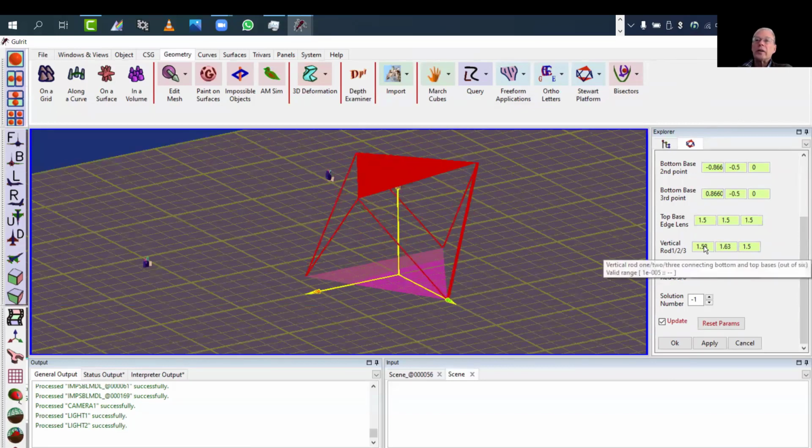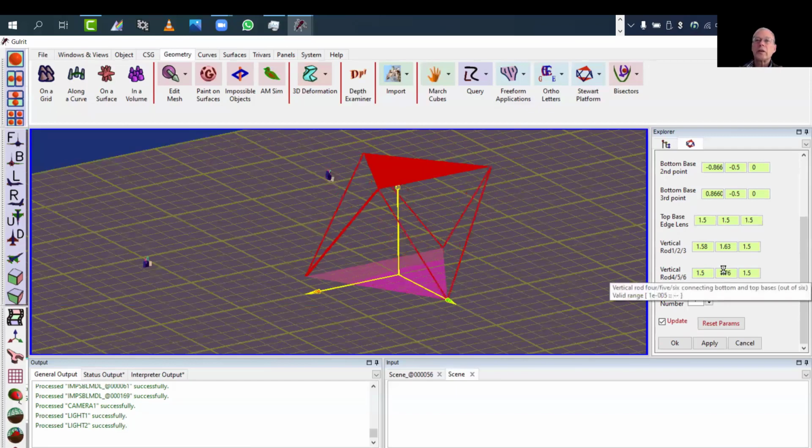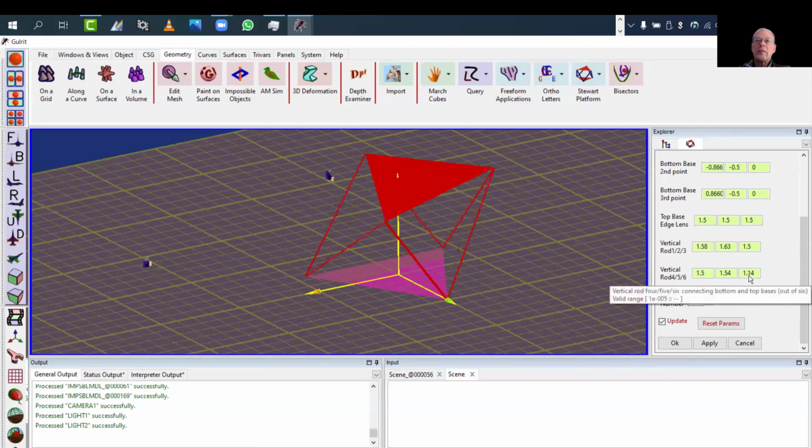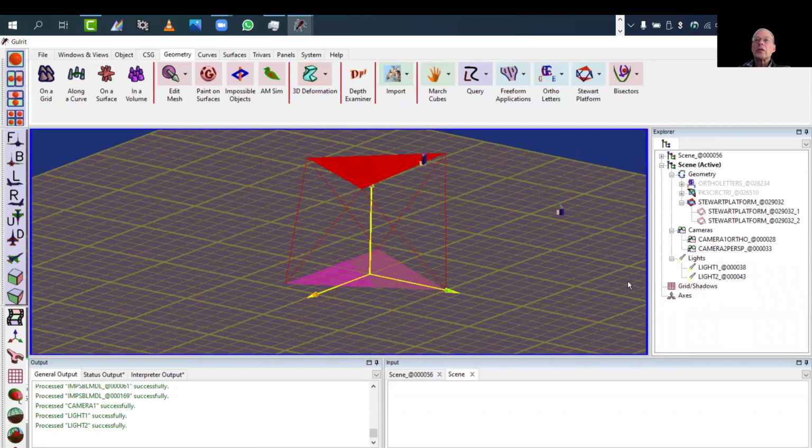There are some singularities. There are, in fact, many solutions here because, if I'm not mistaken, I have 12 quadratic constraints. But if you carefully control the amount of motion that you allow, and always the thick edge is the edge that is actually changing length, you can get the most plausible solution. And this is what we present, the most plausible solution. Okay, so pretty much covered everything here.